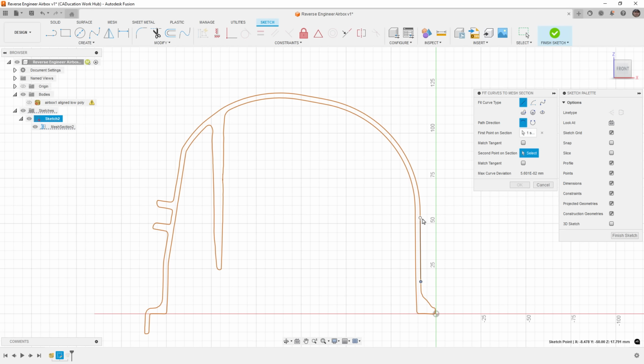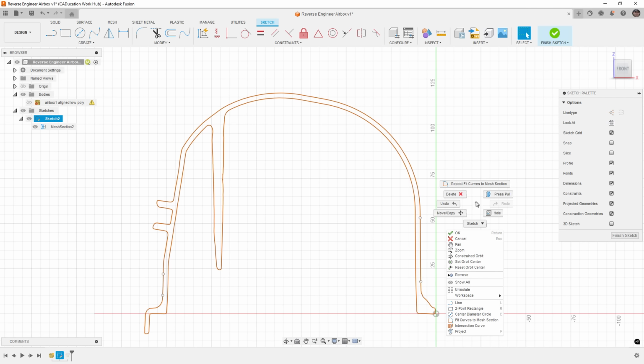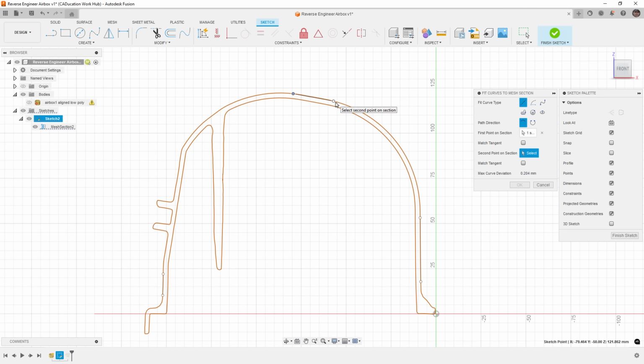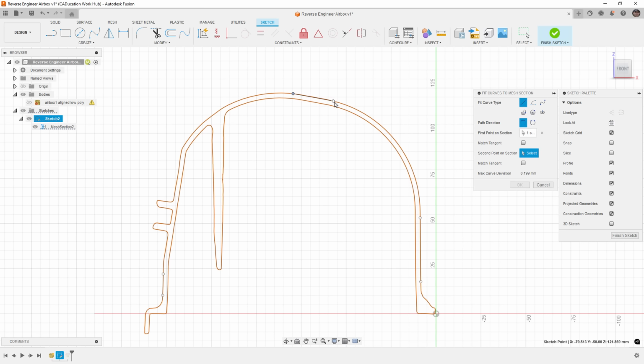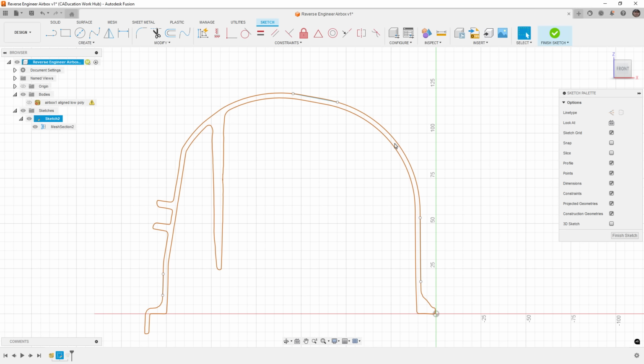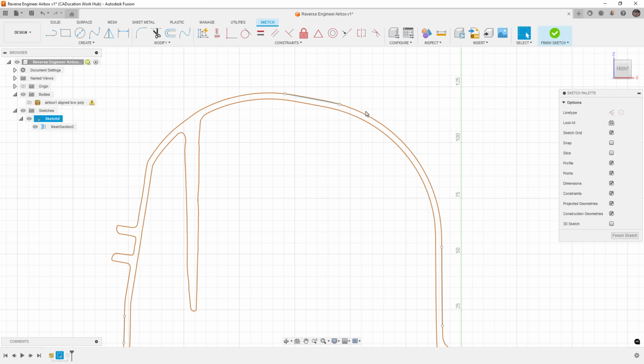So for example, if we wanted a straight line from there to there as a reference, I'm going to right click and repeat that. I'm going to do maybe a straight line here, right click and repeat that. The reason I'm doing a right click and repeat is because if I carry on, it's going to keep making straight lines because it's looking for a second point in the selection. And if you clear this off, you can start a new one. Just my habit of the way that I work is generally I use this right click marking menu. So I'll create a line here and I'll just right click and slide up, basically at 12 o'clock position, and it'll start the tool again. That's just the way that I tend to work. You can certainly do it within the menu and clear out your selection.